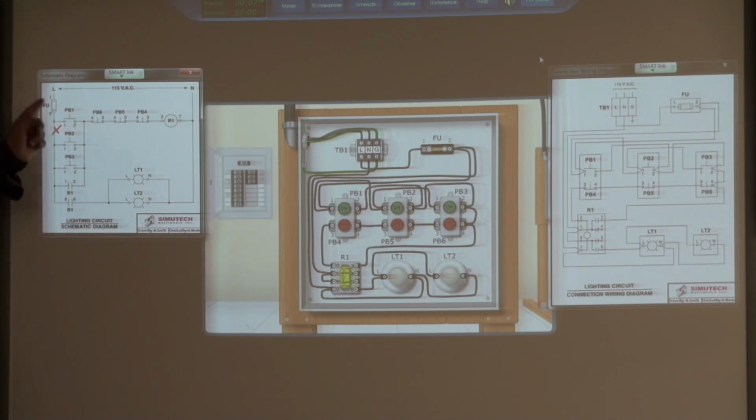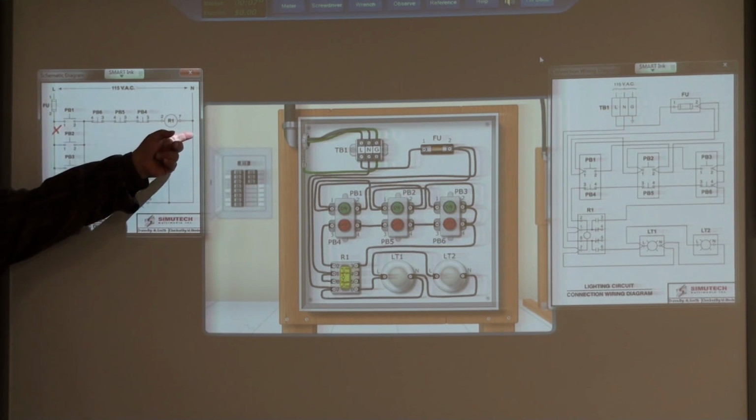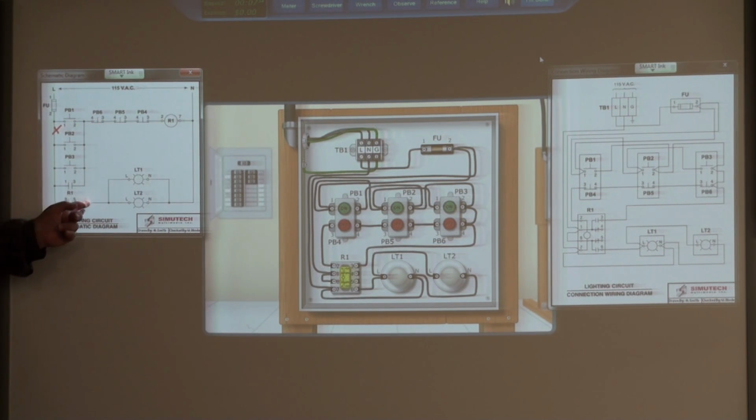Yeah, we'll be able to press PB1. We'll complete the circuit to the coil. With the coil completed, actually, no, it would not come on at all, because it's not getting power. Because there is no return. We engaged the coil, but the wire feeding pin 8 that's ultimately gonna take us to pin 6 is not gonna come on. There is no return point.